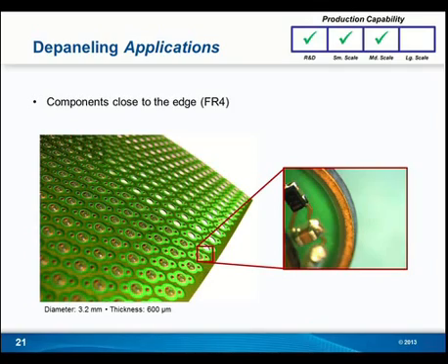You're able to do that. If you're working with a board such as the one that's shown here, you really need a little bit more accuracy. So what you're going to do is read fiducials, like you mentioned here, local fiducials for each separate part. You have your options on whether you want to use local or global fiducials depending on your project. And then the software does the alignment within its internal algorithms and adjusts the X, Y so that you go straight from laser to the material.